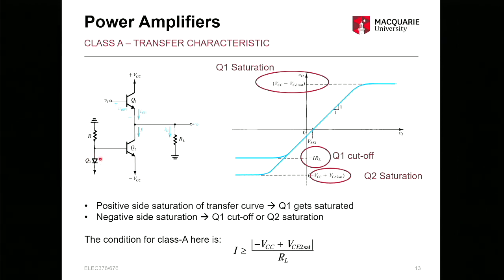So that's mostly there to set the voltage up and keep it constant, but also because its temperature dependence will be the same as for the transistor, because the transistor is just two diodes back to back in the semiconductor layout. As one of those temperature dependencies changes, the VBE required might change, but then the VBE supplied by this will change too to match that.